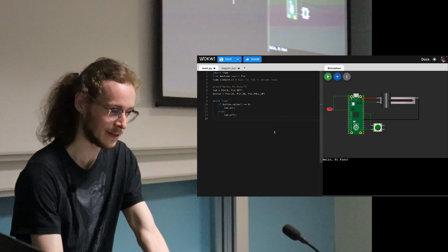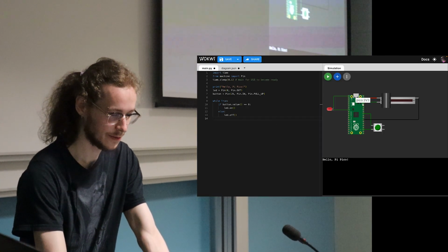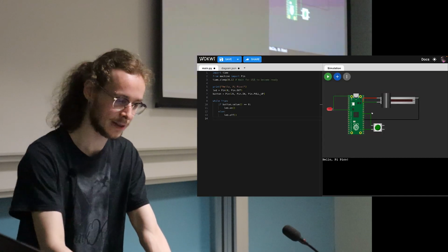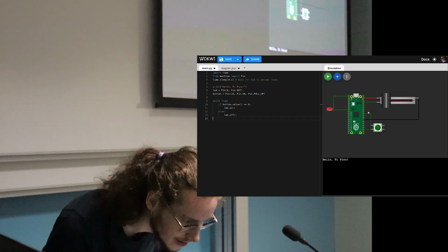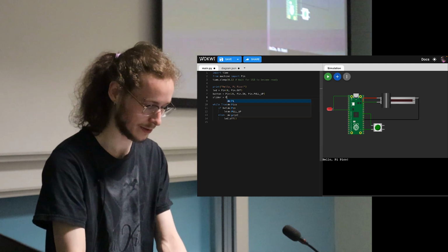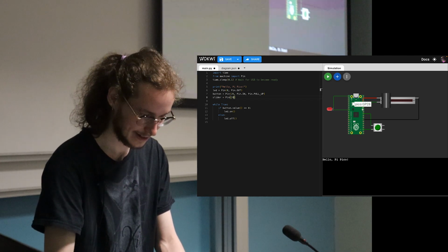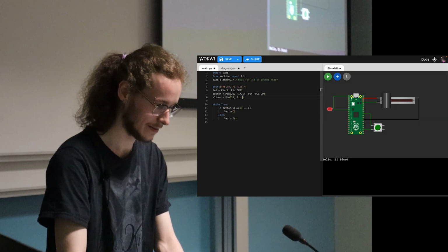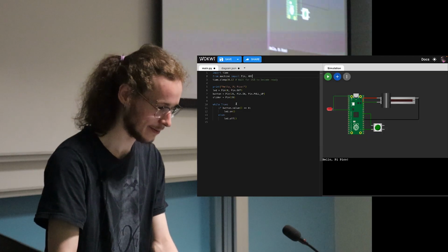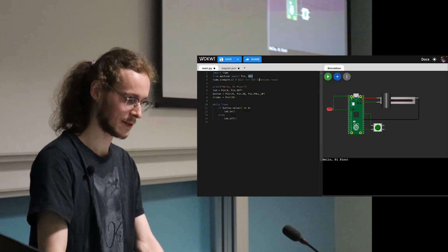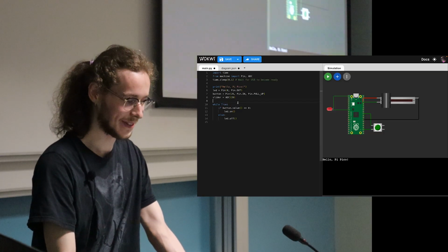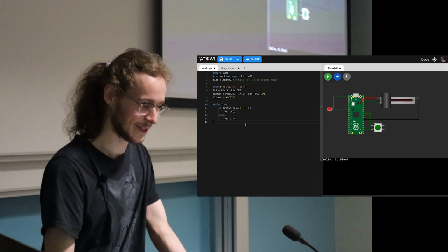So we just need to program this now because that's connected. We've got 3.3 volts in, we've got ground out, and then we have this signal going into a GPIO pin, which is 28, I believe. So let's get slider equals pin. It's 28, right? Pin dot in. Actually, no, that's wrong. We want to import ADC, which is analog to digital converter, and just do that, don't we? Yeah, I think that's right. If it doesn't run, we'll fix it.